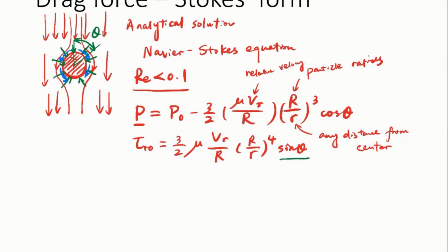So then if we consider the tangential force directly at here, then that's going to be 0, right? Because it's not pushing the particle to the left or to the right. It's at the center of the particle. And the tangential force at here is going to be 0. So if you plug in theta equal to 0 or 180 degrees, you're going to get 0 here.